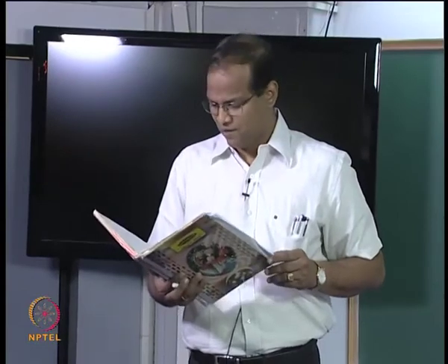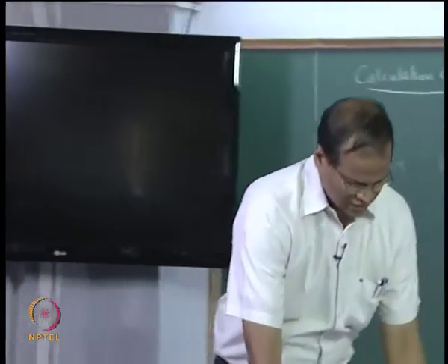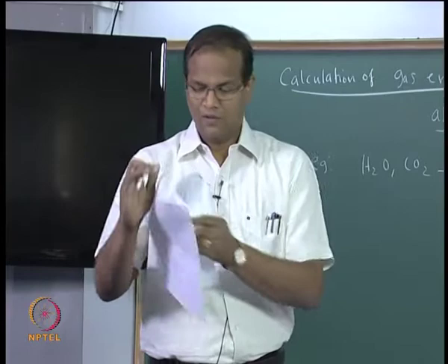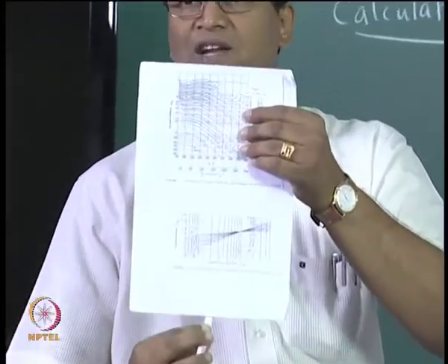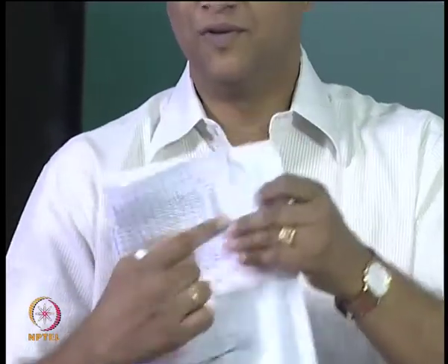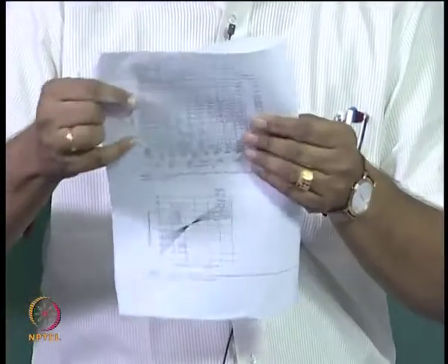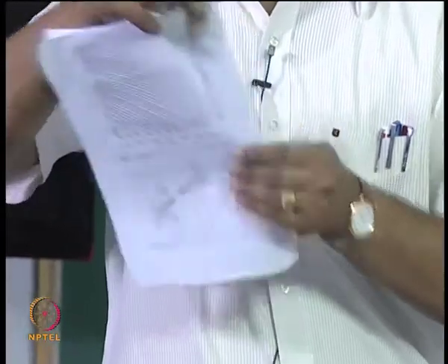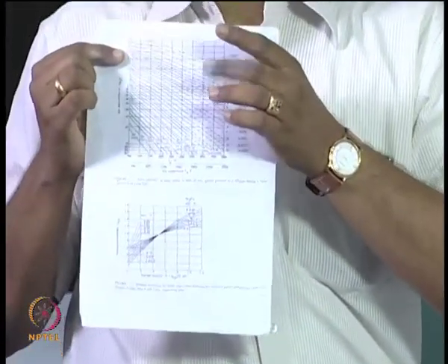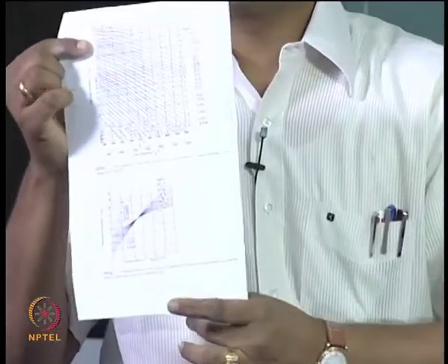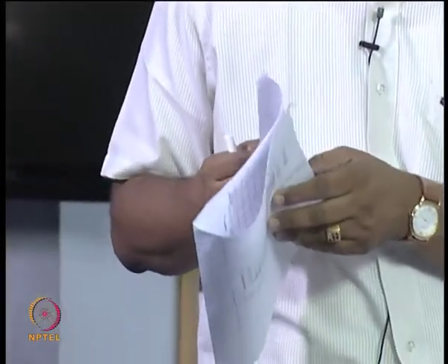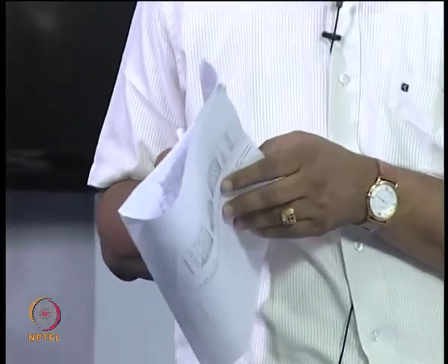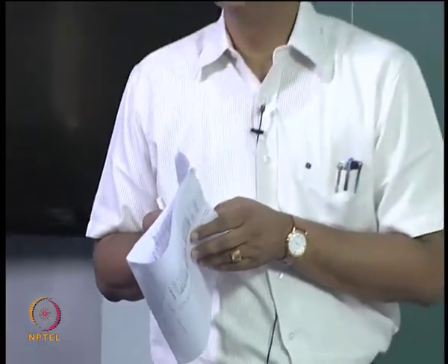Okay. So what is Pw is the partial pressure of water vapor, plus P divided by 2, Pw and Lm. So you can see emissivity of carbon dioxide, correction for the emissivity for pressure other than 1 atmosphere. Emissivity of water vapor, correction for the emissivity of water vapor for pressures other than 1 atmosphere. These two charts will not be used if the total pressure is equal to 1 atmosphere.